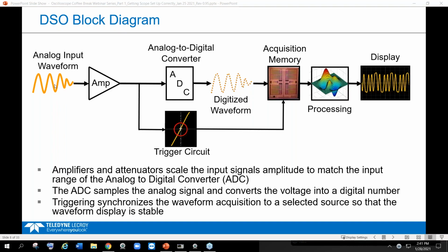If we have a small signal, then a divide by 1 or times 1 probe is going to be helpful, and therefore we'll get, again, the right amplitude into the BNC so that the amplifier, the scope, can deal with it. So that's how it plays in. It's just getting the right signal level at the start to the BNC of the scope. I think that's pretty much it.